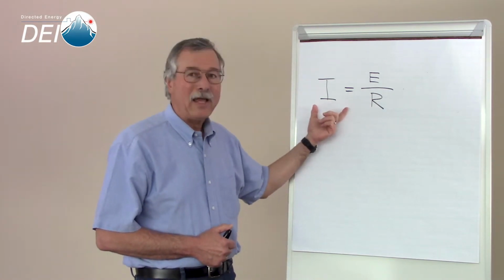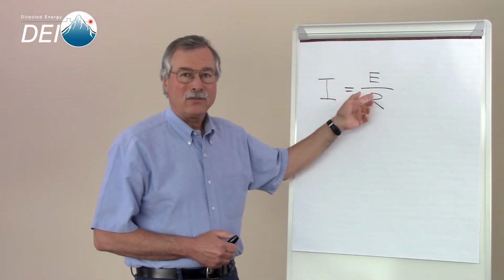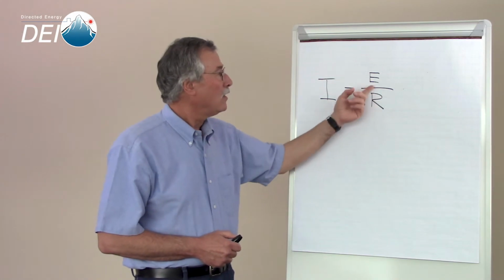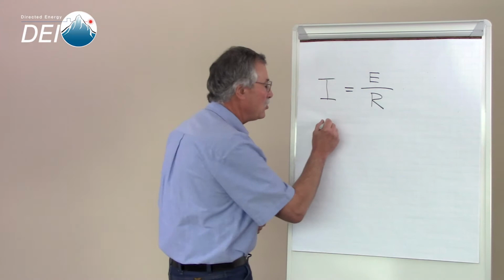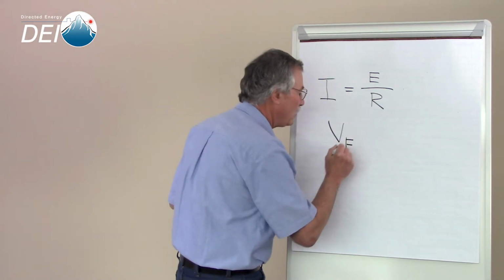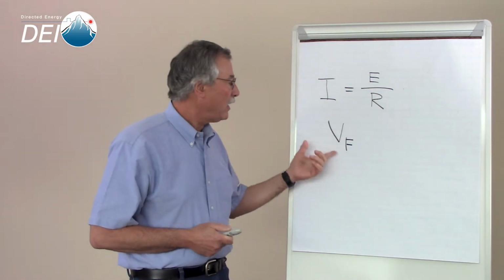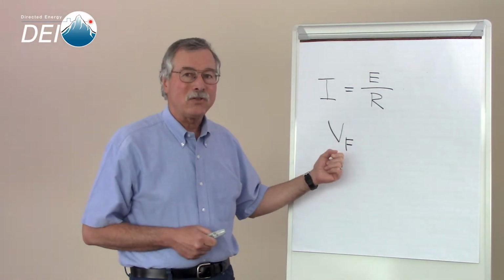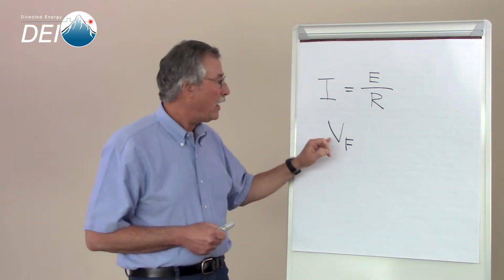It may be 10 amps. That will dictate the voltage. We don't get to say we are going to drive this many volts and this many amps because the voltage will be dictated for us. In the specification sheet, you will see this symbol V sub F, or forward voltage drop. That is the laser diode's characteristic forward voltage drop, and the only thing to remember about that is we have to have a laser diode driver that has at least